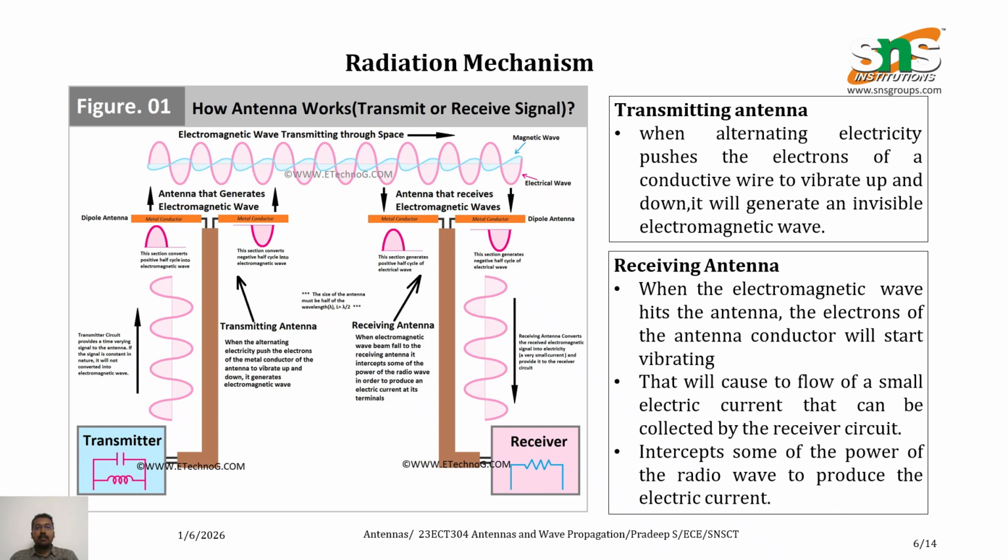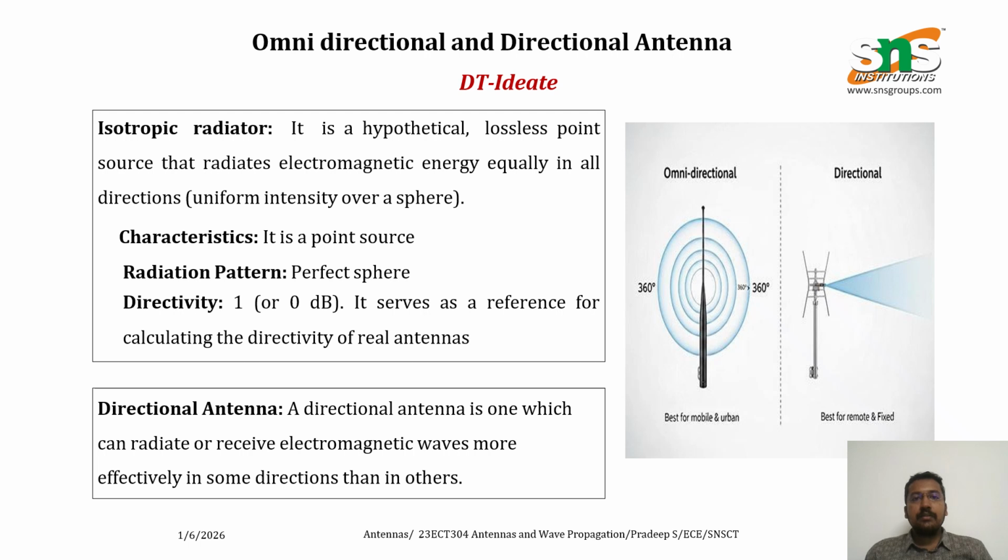As a transmission line begins to flare, the fields radiated by the two wires no longer cancel each other. In a flat configuration, the fields from the two arms reinforce each other in most directions. This transition leads to the geometry of the widely used dipole antenna. The dipole is classified as a standing wave antenna due to its current pattern.